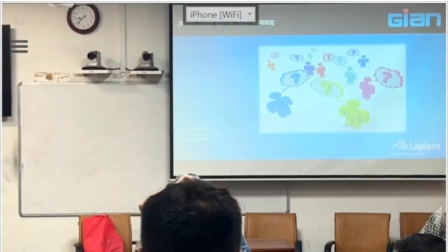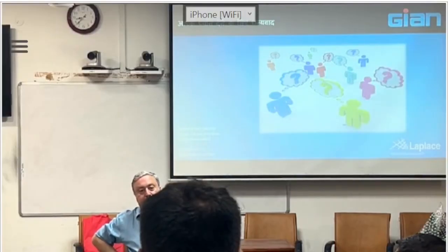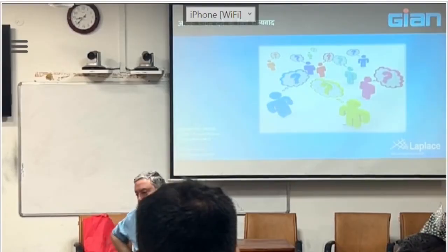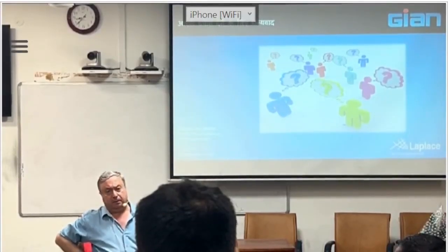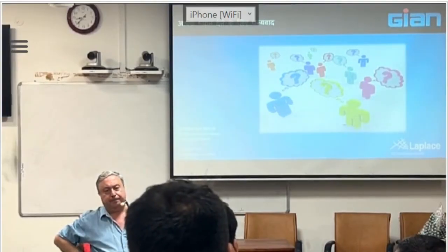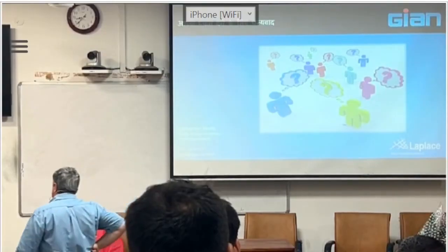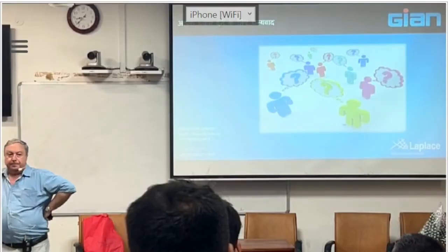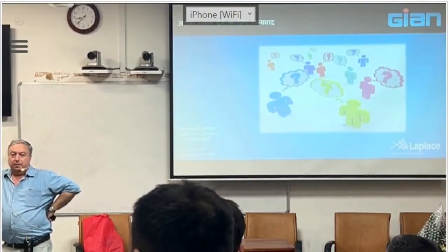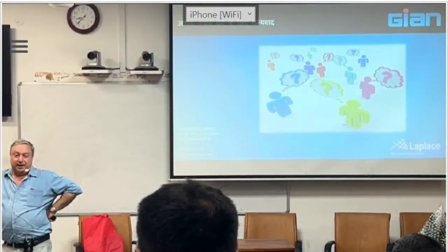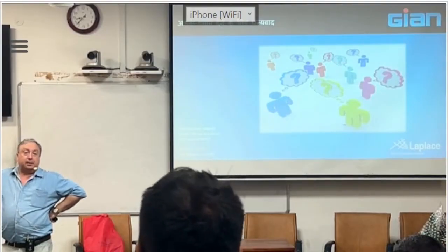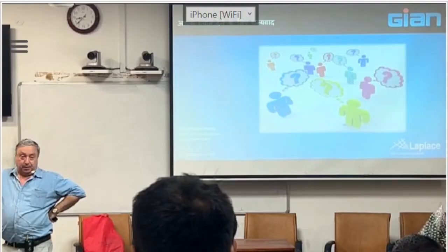Hi sir, actually in indoor lighting for ambience purposes, we use red light, a red LED. Normally, in that red light, how do we adjust the photometric parameters like CRI, CCT, and color purity so that we can get a good light? If you increase the color purity, it may affect the CRI. Yes, even if you cannot define CRI yet, we will speak about that in the next parts of the module.